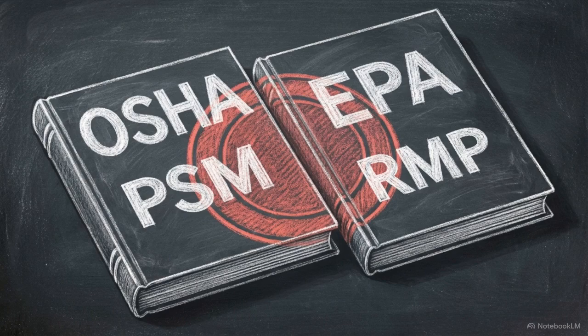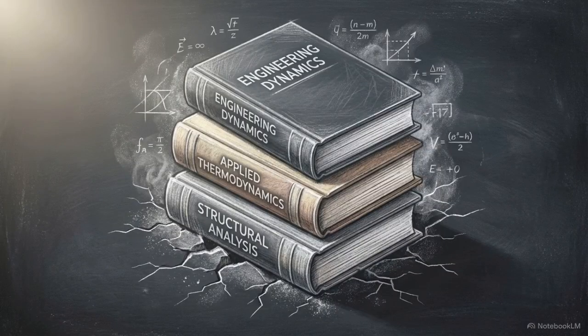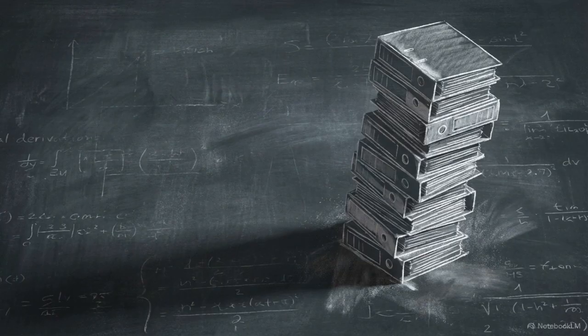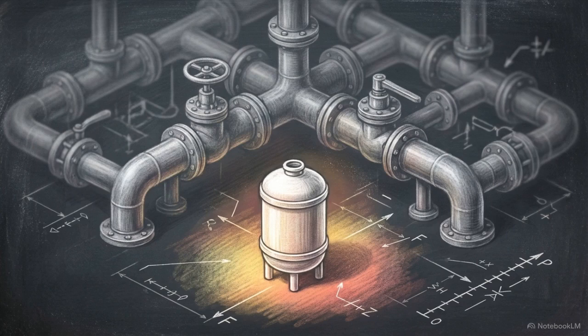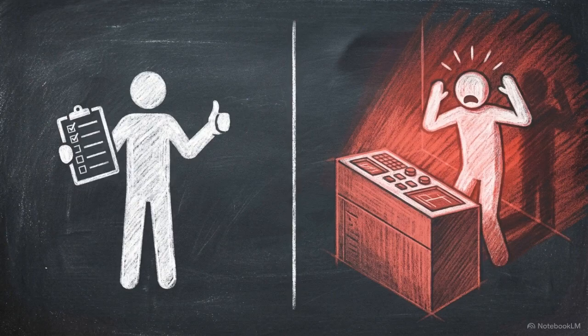Defining these limits is a mandatory requirement under OSHA Process Safety Management and EPA Risk Management Plan regulations. The regulations require that these limits be integrated into the facility's technical documentation, its operating procedures, and its criteria for mechanical integrity. However, many facilities treat this as a paperwork exercise, creating static tables that prioritize easily documented parameters like tank levels, while ignoring critical variables like nitrogen header pressure or acid concentrations. These tables often provide vague instructions, such as "notify supervisor," which offer no actionable guidance during a rapid excursion. These entries satisfy an auditor but fail to assist an operator in a crisis.